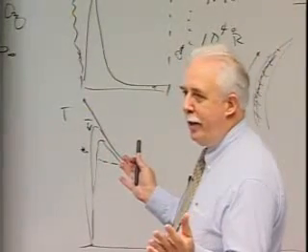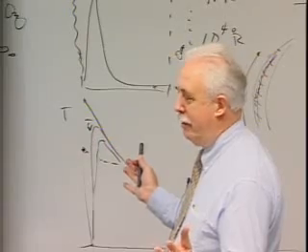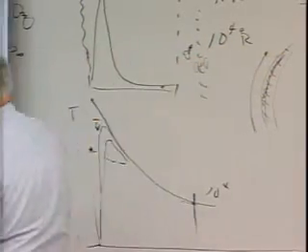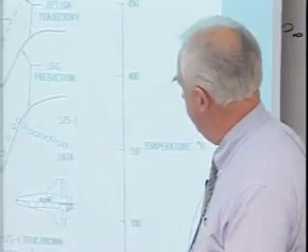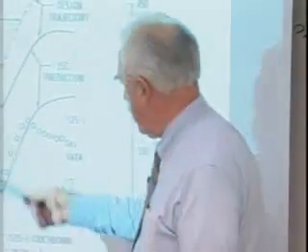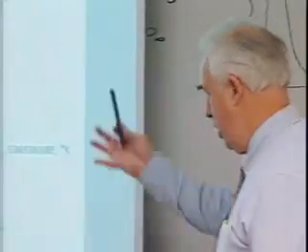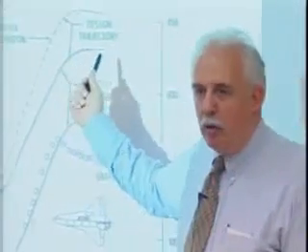Okay, now I think, finally, this is my one and only chart on thermal protection system, which is the real hardware stuff. This is temperature versus time at a mid-body location. Now this is from STS-1. We didn't have data until this time on that flight, which is why I haven't shown much aerothermodynamic data. We only had late time data. Okay, this is the design trajectory coming in from polar orbit.